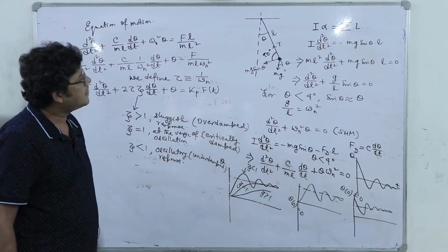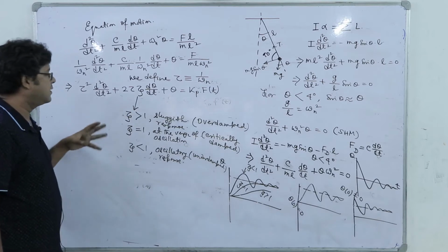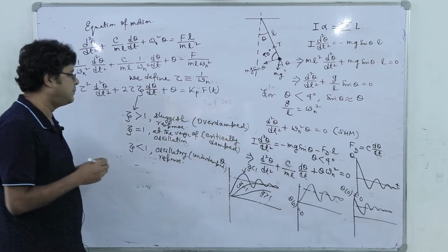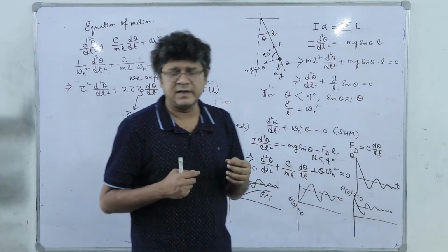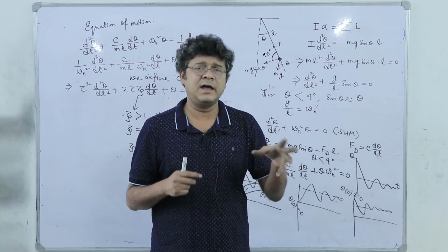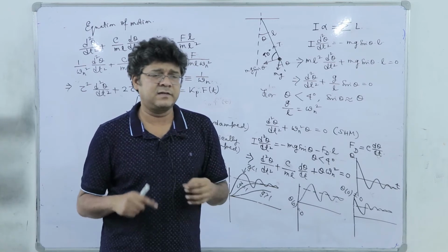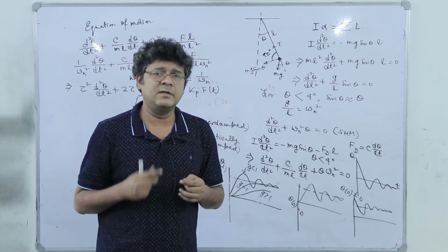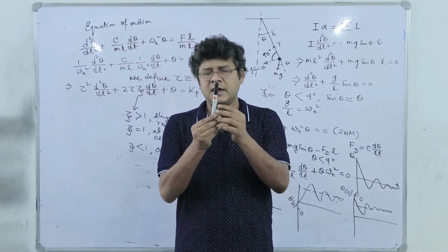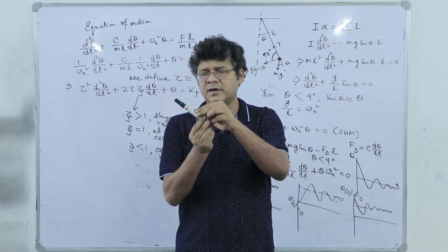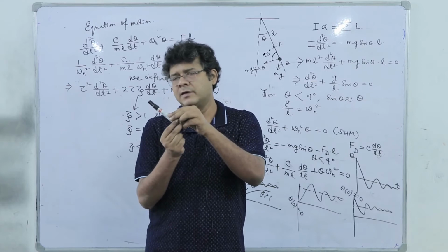Now, in real life, why are we studying this? We have seen different instruments like a pressure gauge, maybe. In a C-type pressure gauge, the arc is extremely sensitive to external pressure. So what will happen? If initially it is 0 and finally it is, say, 2, the needle will displace and indicate these 2 atmospheres.